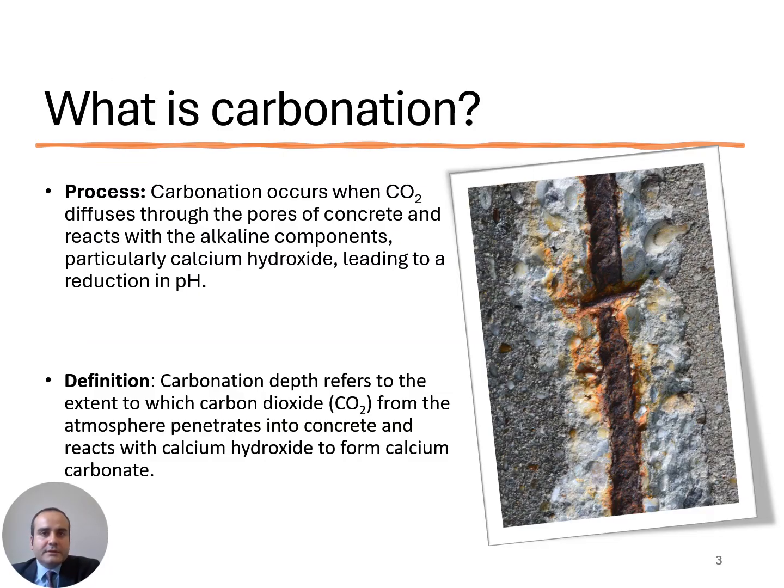Carbonation of concrete is a chemical process that occurs when carbon dioxide from the air penetrates the concrete surface and reacts with calcium hydroxide present in the concrete. This reaction produces calcium carbonate. In other words, the process begins with the diffusion of CO2 into the concrete, where it encounters calcium hydroxide and forms calcium carbonate and water.